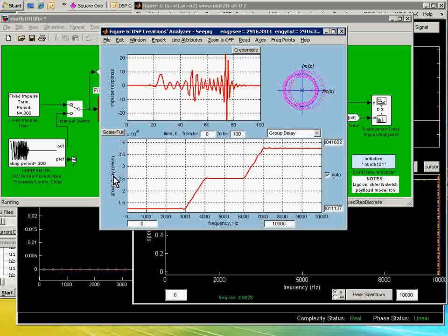We could have group delay in seconds, but that's not nearly as informative to us, because when we see this mid-span value of about 50 and this sort of symmetric behavior about that, well, we start feeling pretty good. We start thinking we probably could build a way to emulate that group delay with an all-pass filter of a size of about 101 coefficients, more or less double what the mid-span is. Well, of course, it's not going to be that we want. It's going to be sort of like an inverse.